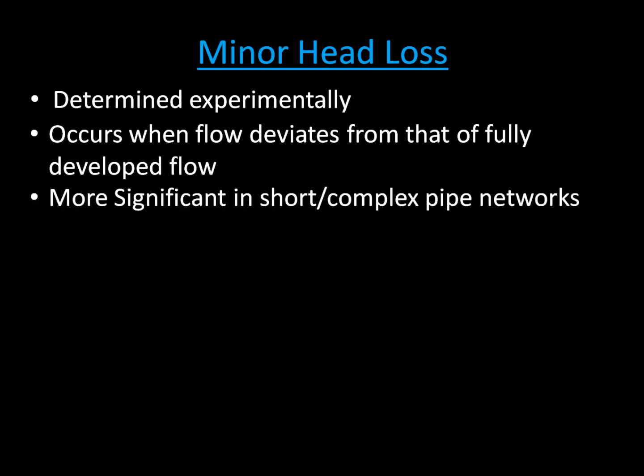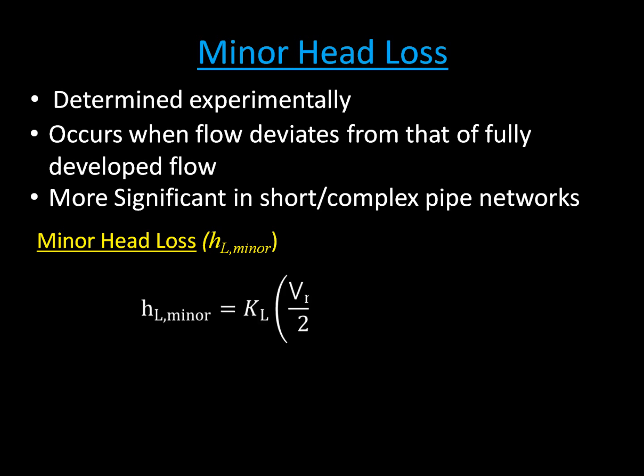This is more significant in short, complex pipe networks. I mentioned this in the major head loss video. If I have a long segment of pipe, major head loss is going to be the dominating factor. But if I have a short set of pipes with a lot of different of these connections or bends or valves, minor head loss may actually be the dominant factor.